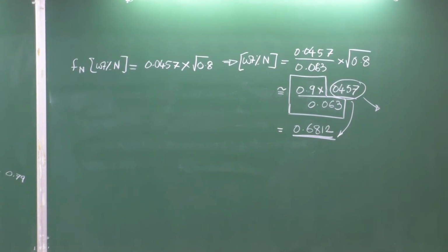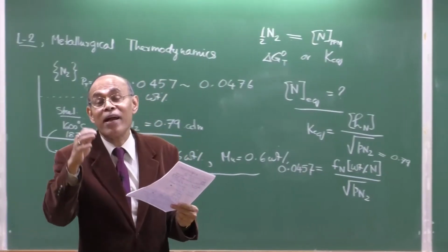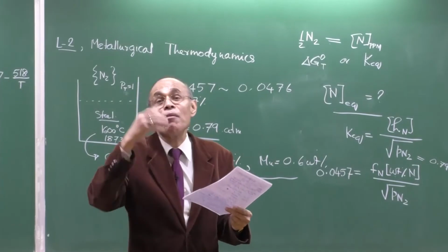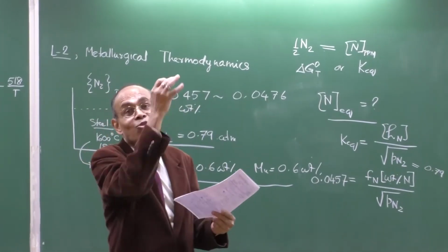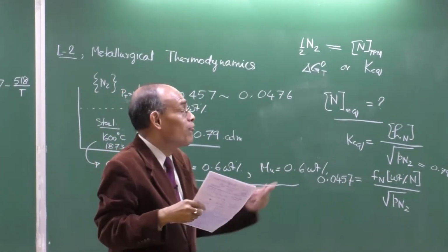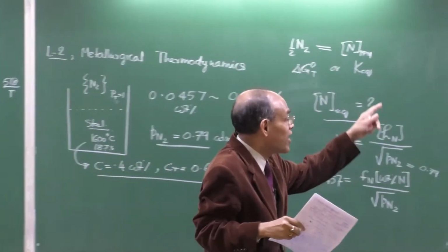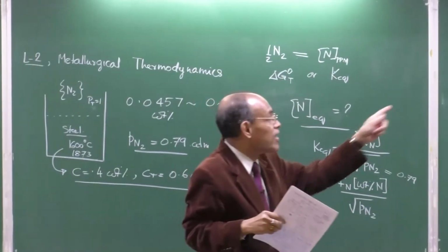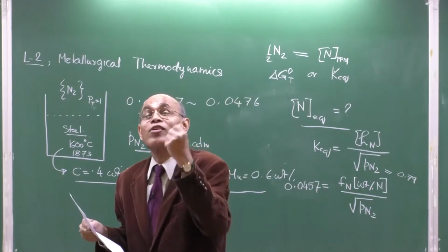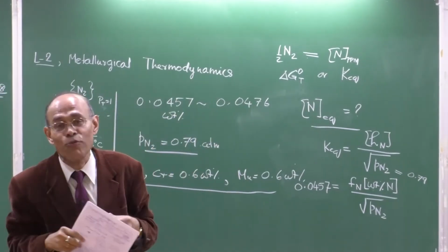So alloy steels will tend to dissolve much nitrogen. Okay? So an alloy steel containing chromium and manganese will require an extensive degassing operation to drive it out. If you introduce titanium, which is again a strong nitride forming element, the solubility would further increase.